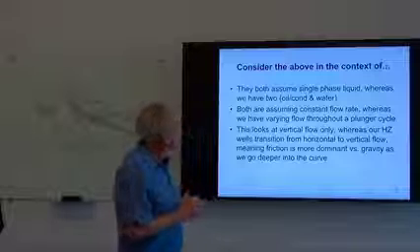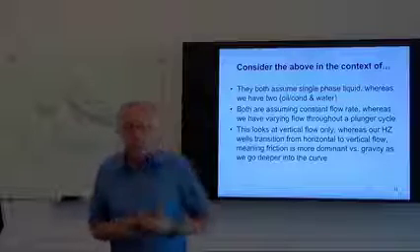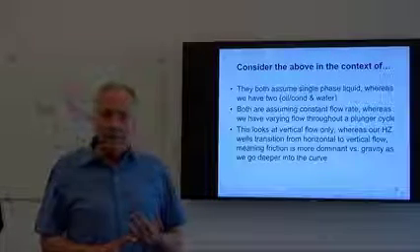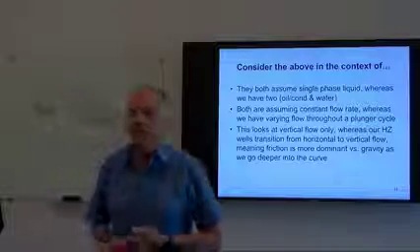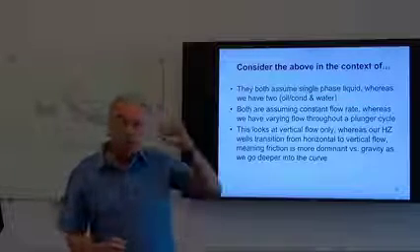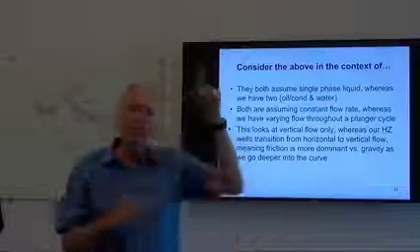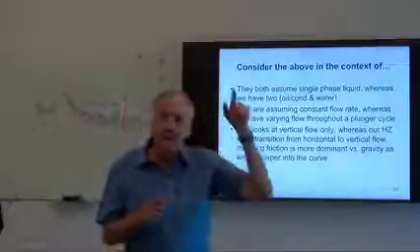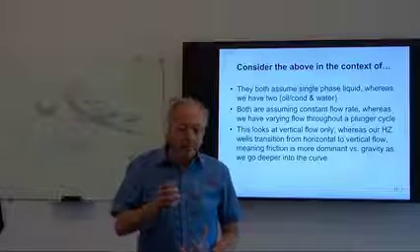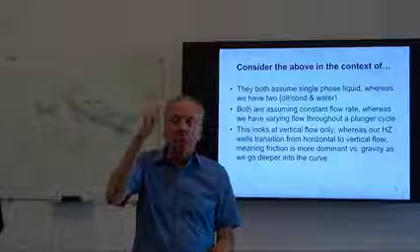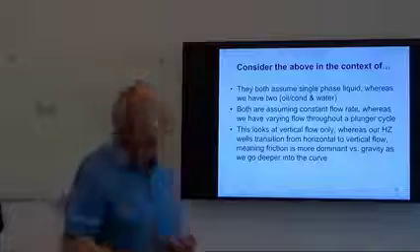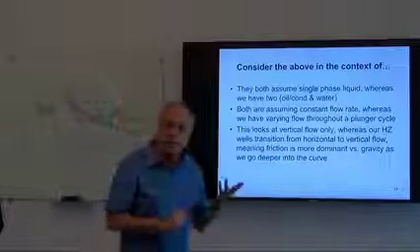Also, these are assuming a constant flow rate, and in the plunger lift case, we have varying flow rates. So in a conventional operation where we're shutting in to let the plunger fall to bottom, we're waiting some period of time to build pressure, we open at surface, the plunger comes up, we're getting a certain flow rate. With that head gas coming above the plunger, we're starting with an inflow rate, so we've got different flowing conditions, we've got lower pressures up high, we have more gas expansion, and there's going to be this difference across the bottom to top.